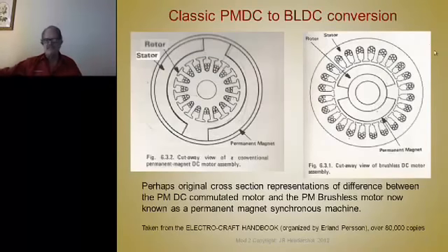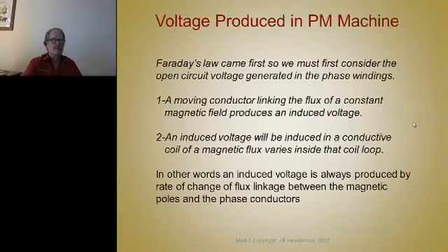If you drive either one of these motors, spin them, and look at the output voltage, you see what the back EMF is. It's very easy to see. You don't see the back EMF in an induction motor, but you can in these synchronous brushless permanent magnet machines. So that's where the terminology came from, as it was converted from an inside-out DC motor.